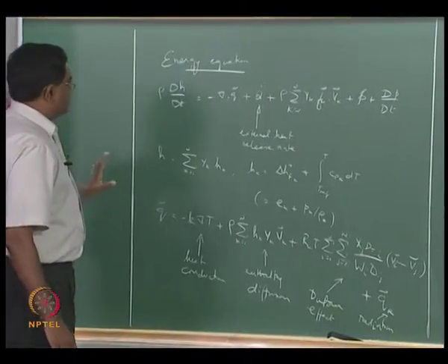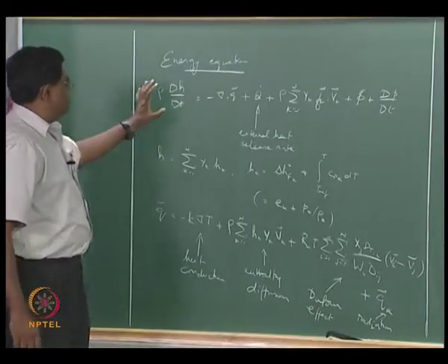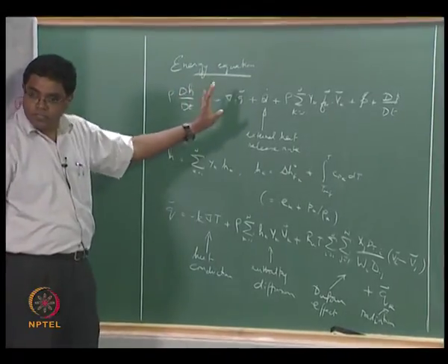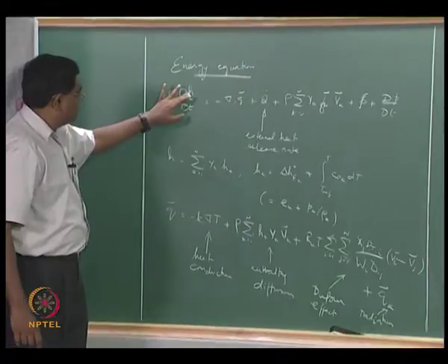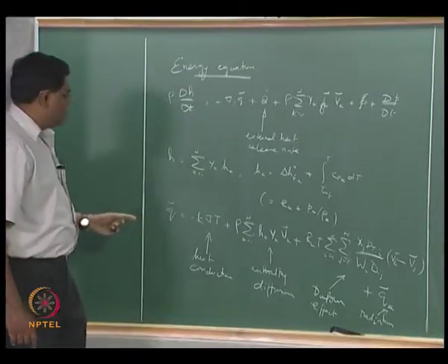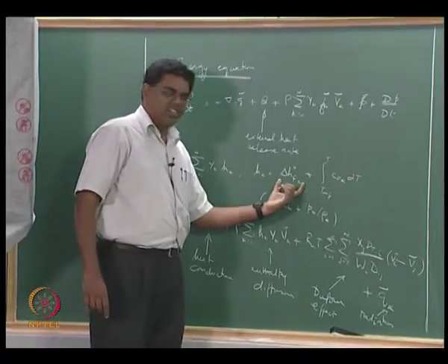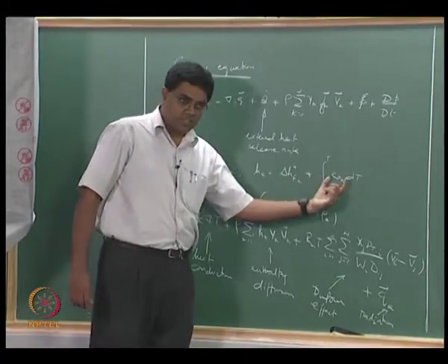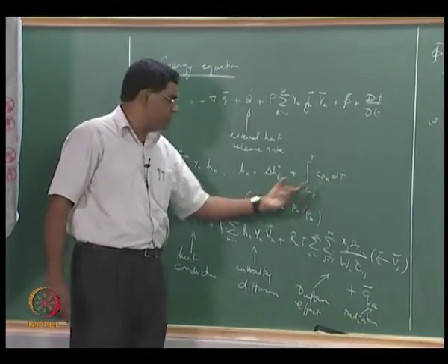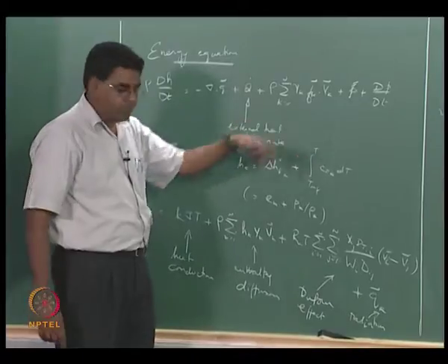We were looking at the energy equation, so here we rewrite this again, where we now look at term by term. So this is essentially the inertial term of enthalpy flux, right? And so the enthalpy is now of the mixture, and so H is now written as sigma Yk hk, where hk is now the specific enthalpy of species K, which can in turn be written as the standard heat of formation of that species plus the sensible enthalpy. Okay, this is a specific sensible enthalpy of species K, and temperature is an unknown that is sitting on top of this integral here as an upper bound.